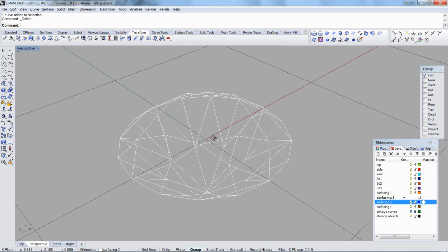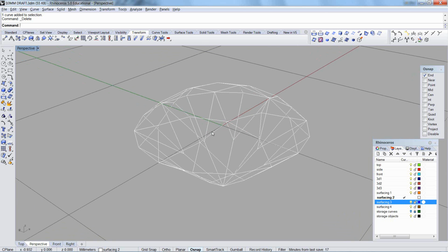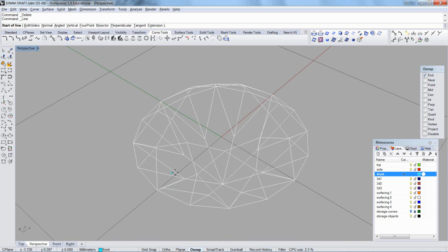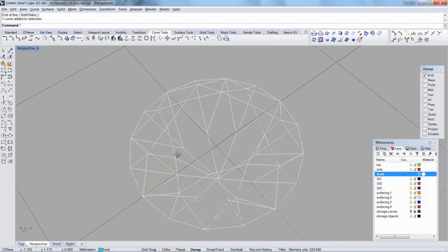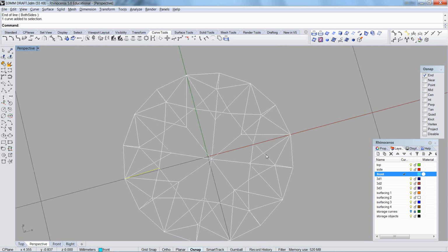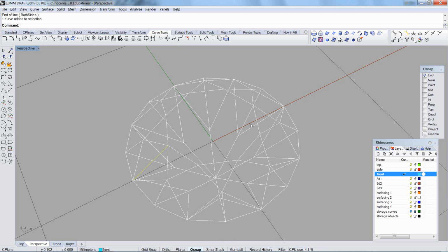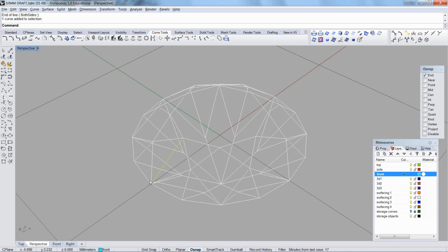Okay, to facet the stone, we need to do the faceting for the bezel facets and the main facets first. So, need to draw a line that I'm going to extrude to make that bezel facet. Here to here, there's my bezel facet. You want to pick one of the ones on the 4 quadrants, either left or right or up and down. Following the video, let's do it on the left side here. From the top of the bezel facet to the bottom.